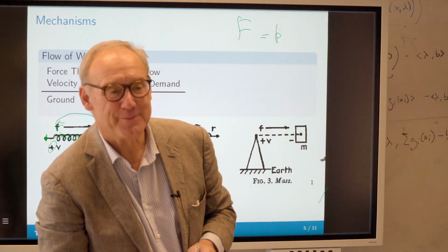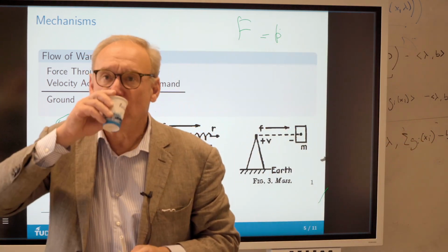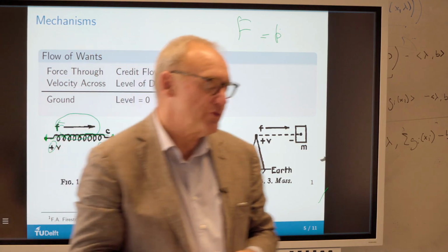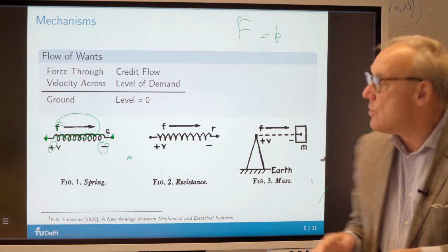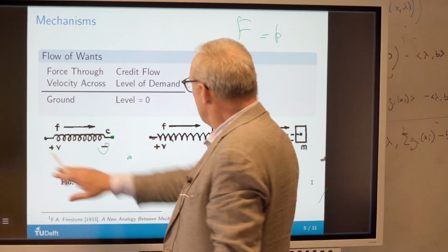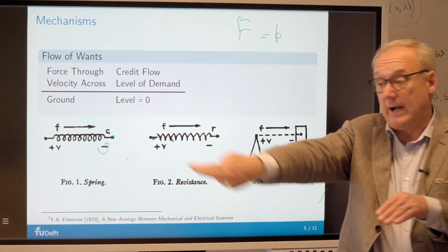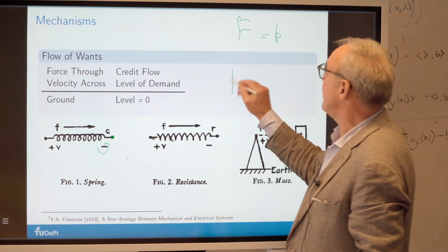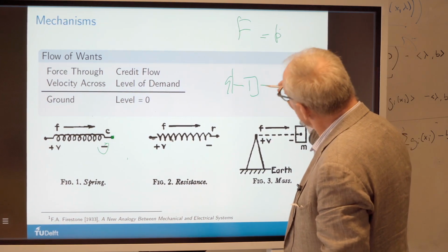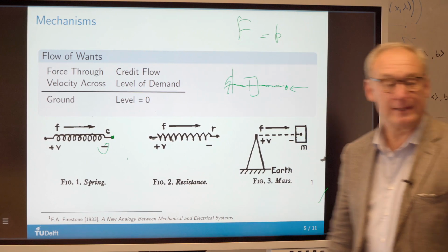Okay. So, the picture of force that we get from Newton is that of flow lines through the element. So for the spring, it's very easy to imagine. For this damper too, it's just flowing right through. So you attach this damper, and you put a force on it here. The force is flowing through into the wall, right?